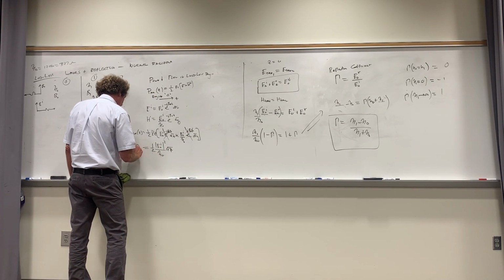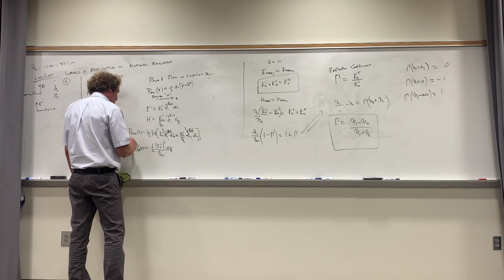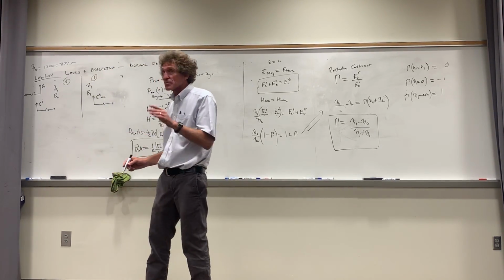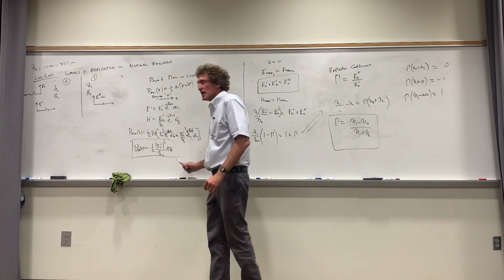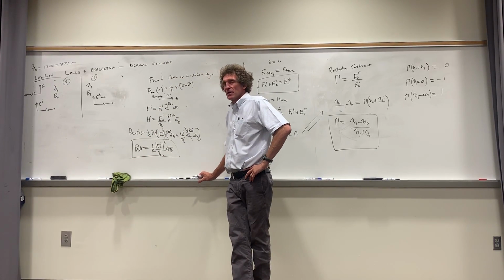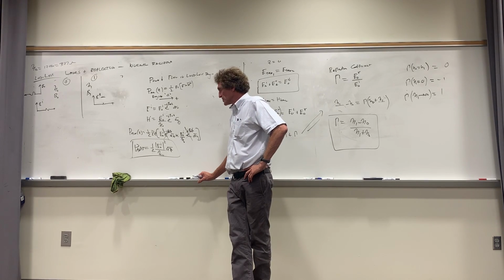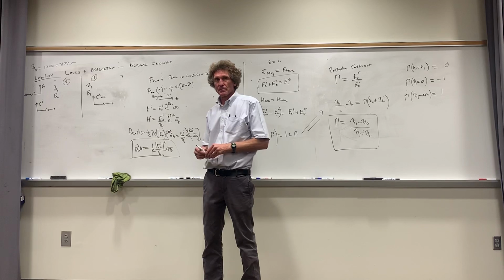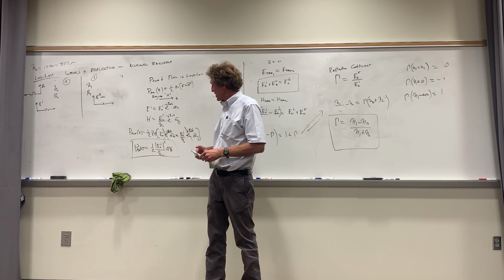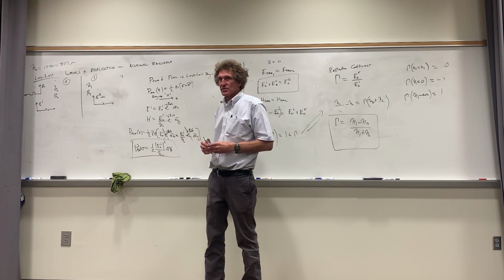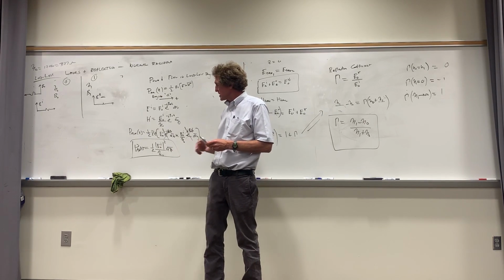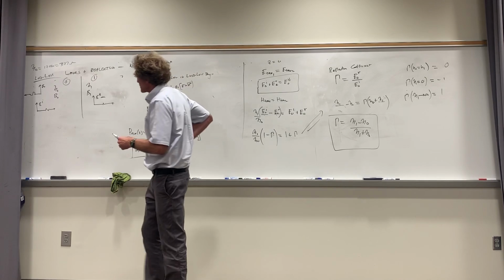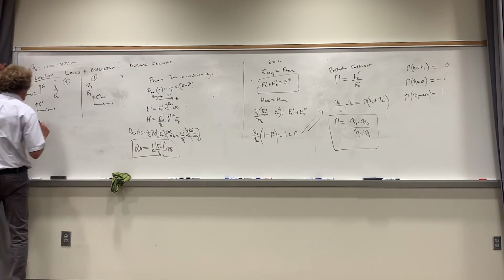And in general, whenever you're talking about power flow in a lossless region, or approximately lossless, if you have the electric field, that's the only thing you need. If you have the direction of propagation, it assumes the direction of propagation. You take that electric field, square the value, divide it by eta naught, and multiply it by 1/2. That gives you the power in watts per meter squared. The az is the direction of propagation. Are you with me? Now, if you think about power flow in this problem, I hope you can see this.